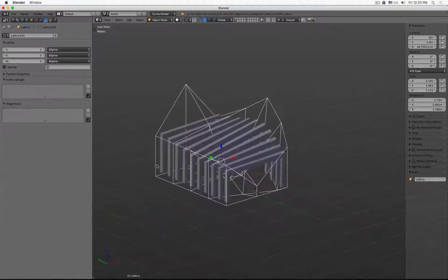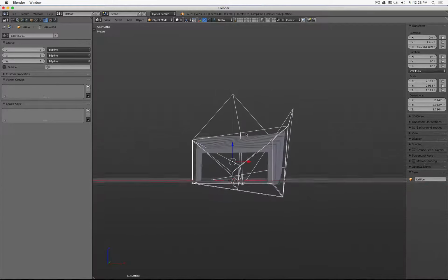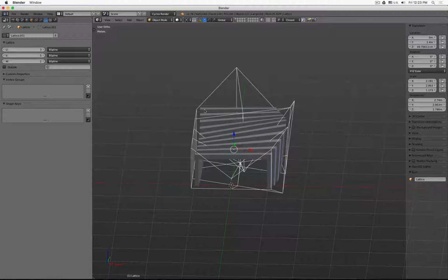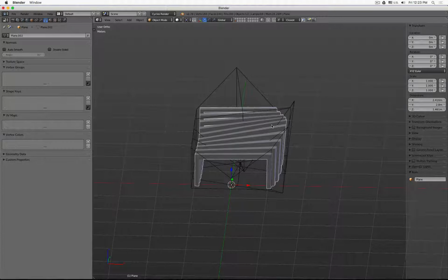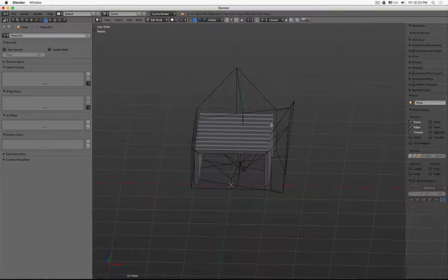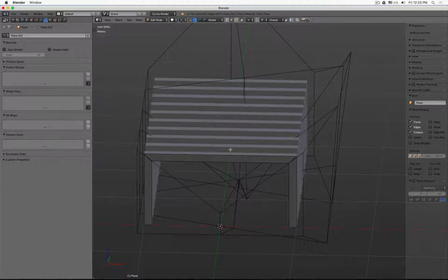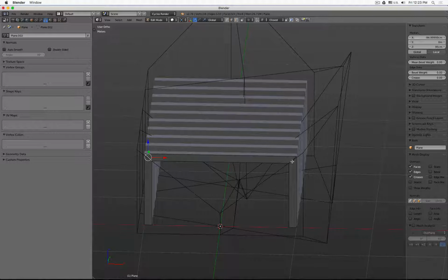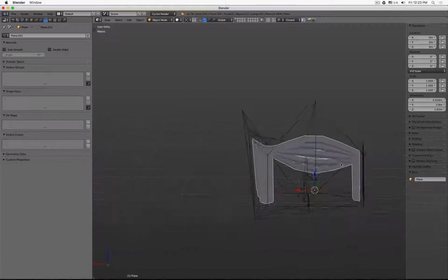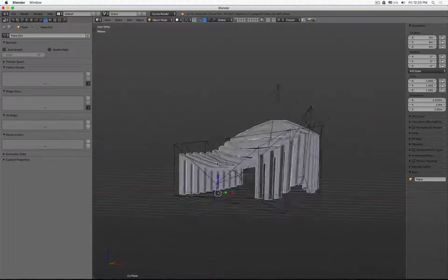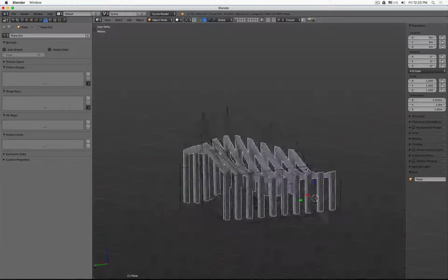You see, these lines actually go up and down, but they don't really arc. Well, actually, kind of like I have a C here. The main reason for that is the mesh object doesn't have any geometry there. I only work with these points. So if I, let's say, here add more loop cuts, bang, see, we have more geometry and we can deform this more.